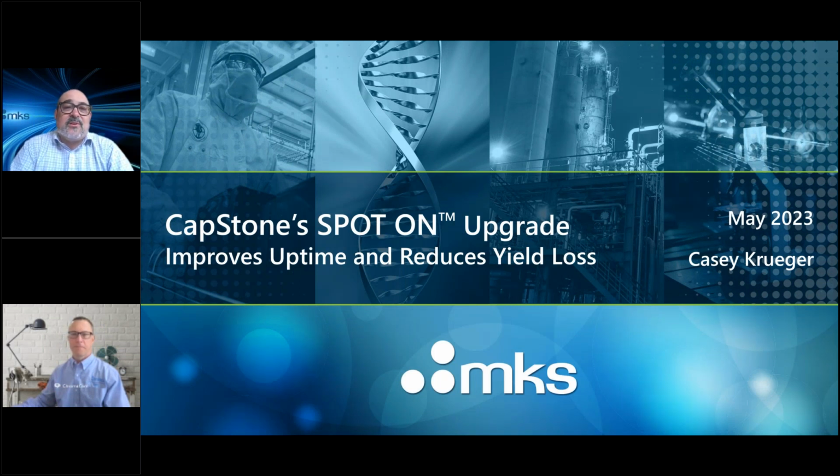It's always an exciting opportunity when we get a chance to talk about the latest innovations in flex drilling. Today's webinar focuses on how Flex PCB manufacturers can leverage CapStone's spot-on upgrade feature to increase their competitiveness by improving the quality of blind vias to increase yield.